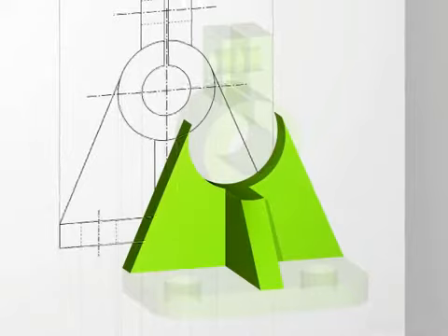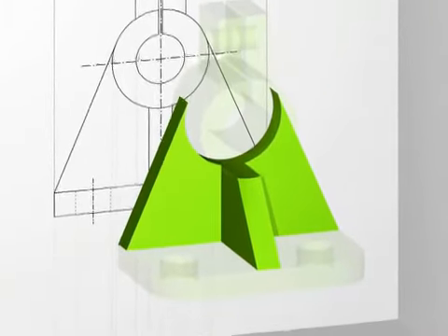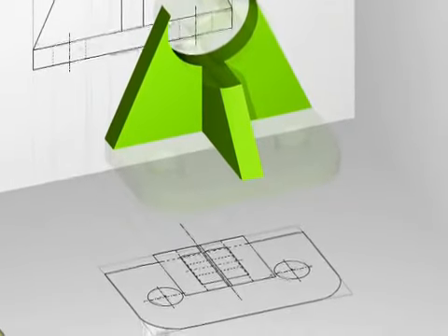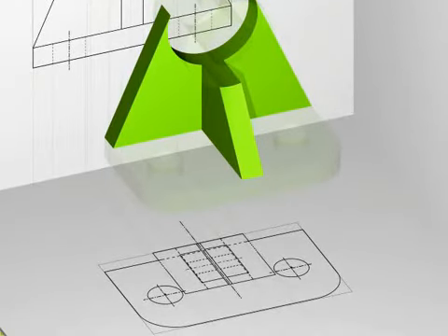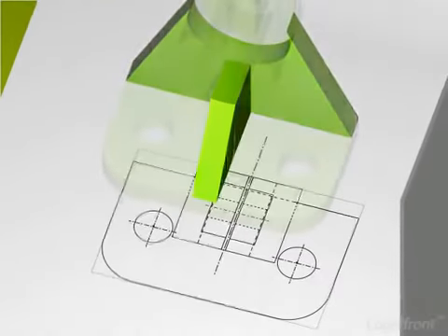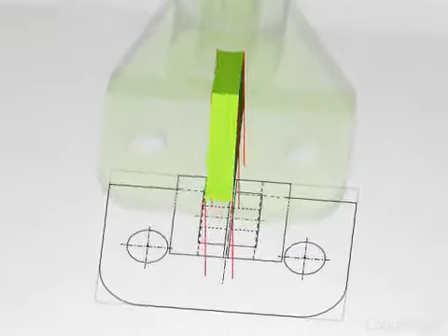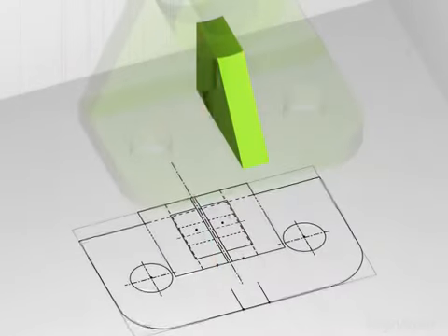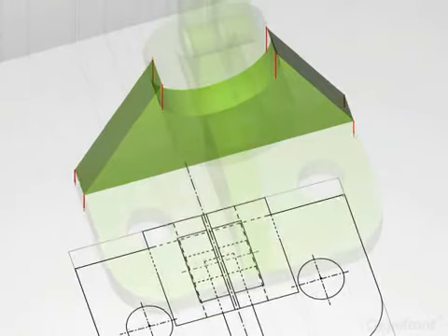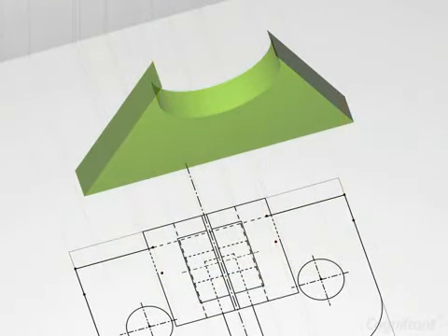Complete the top view by drawing the ribs. The ribs are connected between base plate and the cylinder. There are two kinds of ribs in this object. Supporting rib at the center of a cylinder and tangent ribs on two sides of the cylinder.